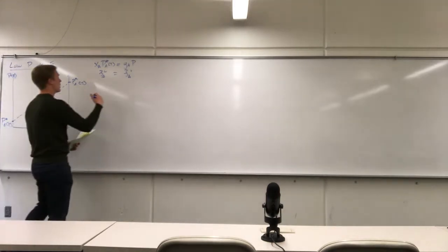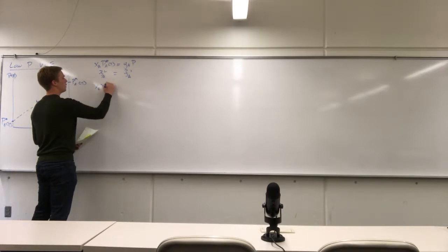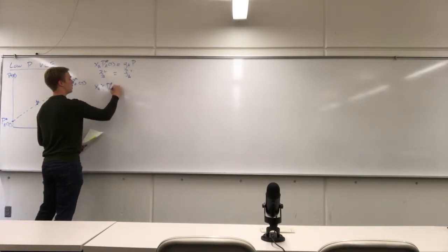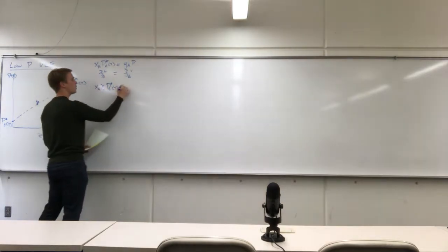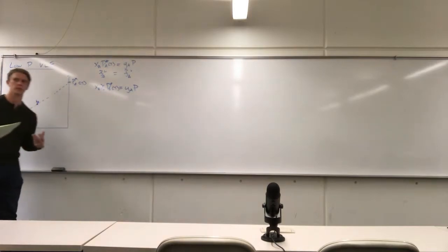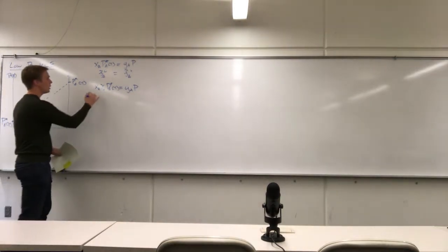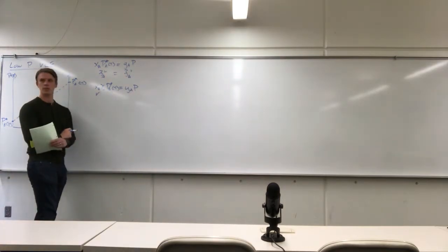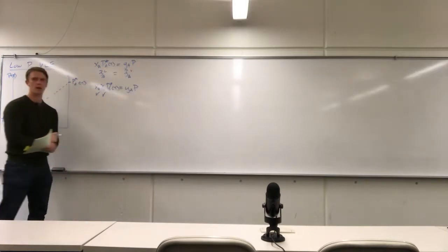Now what we'll be talking about today is when it's slightly more complicated. In this case, we're only considering ideality and non-ideality in the liquid phase, and if we consider an ideal gas vapor phase, then we have a relationship. So if we start from the liquid, we know our composition, because we're totally there, we just made it. We have an activity coefficient model.